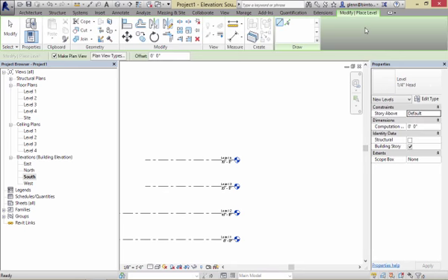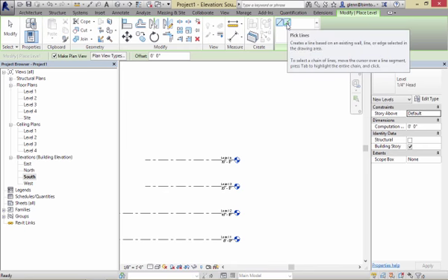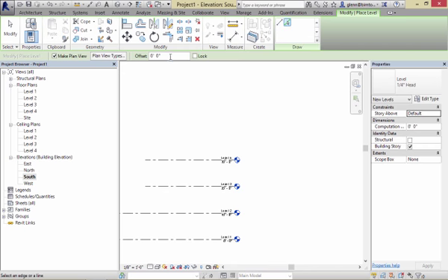Under level, you have the option of drawing a level. That's right here, drawing a line. The other one that I always tend to gravitate towards is the green line. The green line is always this notion of picking something and using that as the basis for the geometry. So I'm going to choose the other tool, which is all about picking. Okay. And what I'm going to do is say I'll pick, and as I pick things, what I want to do is offset the distance.